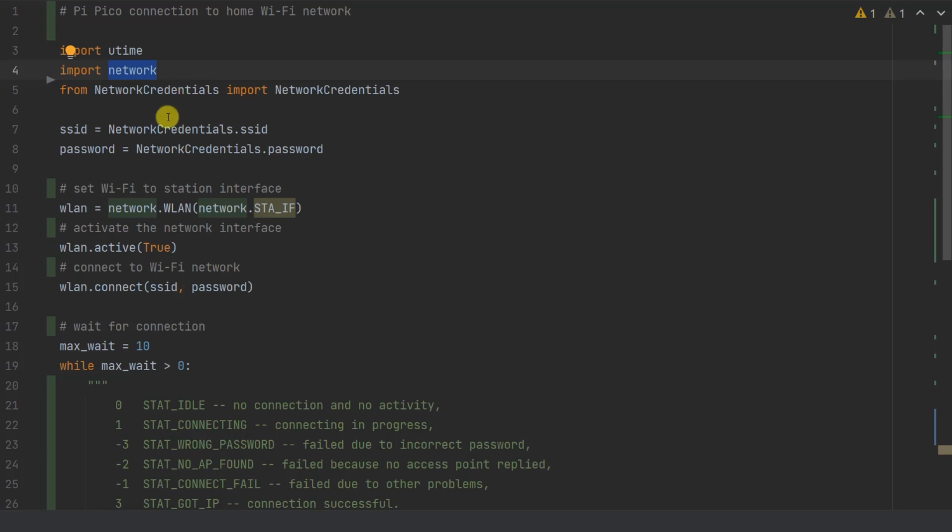In this block of code, we are going to connect up to my home Wi-Fi network, and for that we need to have the network ID. This is the SSID, and that is the broadcast name that your Wi-Fi network uses. We'll of course then need the password. And all I've done here is I have just buried my actual values inside a little class called network credentials, and that's just so that I don't have to keep blanking them out on this video. But really all you need to do here is just put a string in here with whatever happens to be your Wi-Fi connection.